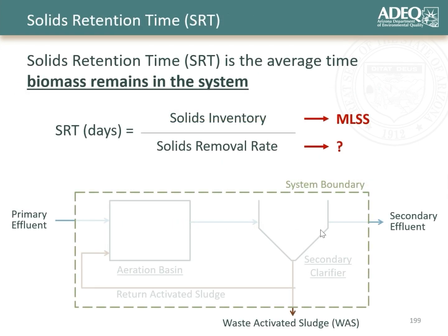Now, a very important parameter, maybe one of the most important parameters for operating your activated sludge system, is the solids retention time. This is once again the average amount of time the biomass remains in the system. And the way this is calculated is you first look at how much solids you have in your system, similar to the volume of the reactor we had with the HRT.